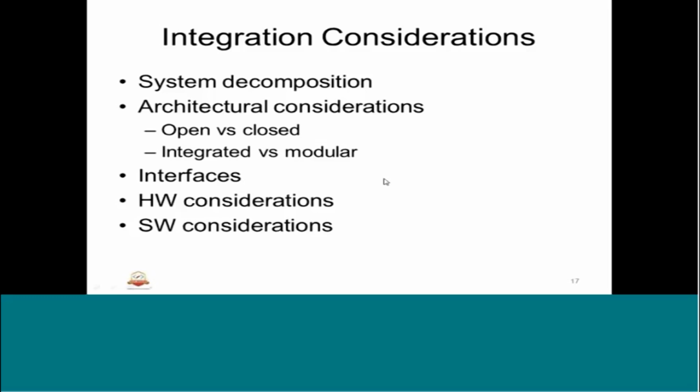Then we need to understand hardware considerations. We need to know what sort of hardware is used, whether it's a real end target or an evaluation board. All this will have to be considered. And tools, of course, can have a hardware dependency or hardware simulation. This is very much important, particularly in bigger systems where we have automated test equipments, ATEs. So hardware consideration is one of the important elements of the integration testing. It is called HSIT, hardware software integration testing.